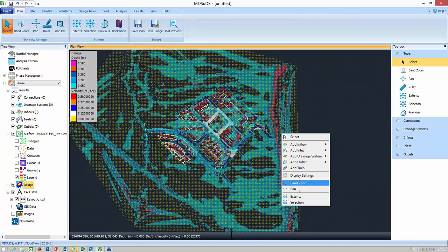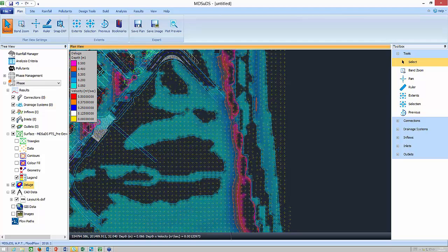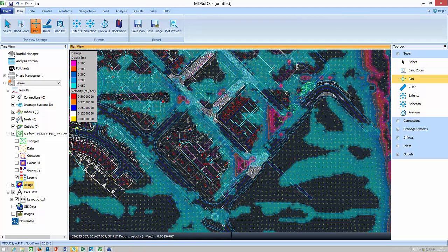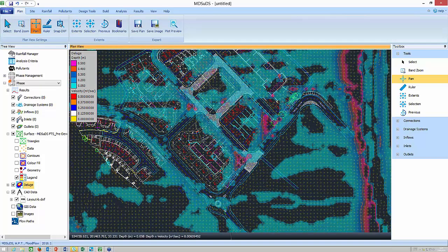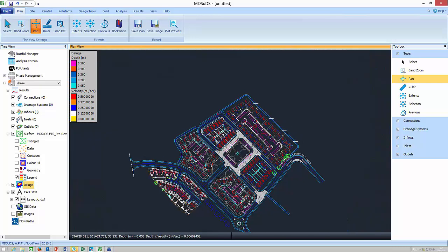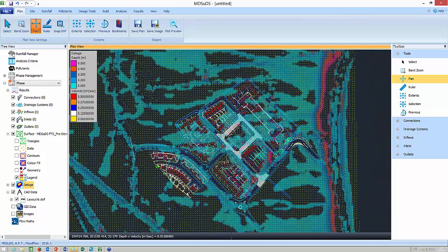And as we kind of suspected, if I right click and just pan in a little bit, there are a lot of direction arrows now, showing us the direction of the flow of water across the surface. And then the color of the grid squares will tell me the depth of water. So it's fairly shallow. If I stop my mouse over here, the light blue is anything between 50 millimeters and 200 millimeters deep. So it's fairly shallow flow coming across the terrain.